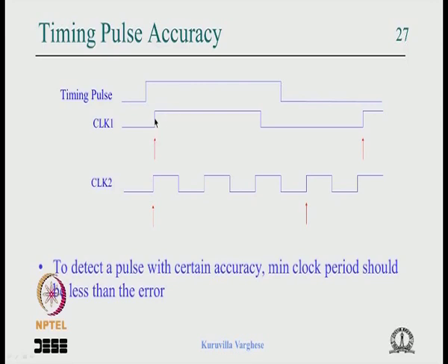But what happens now, what we capture is that we check at this active edge that it is 1, and at this active edge it is 0. So the time the state machine detects is this time period, not this time period. So that is the issue. And suppose you use a slightly higher clock frequency, there are positive edges here. So we are sampling at all edges. Here before, it was detected as 0, at this point it detects that it is going high, and you see here it is 1, here it is 0.